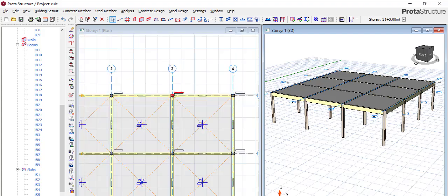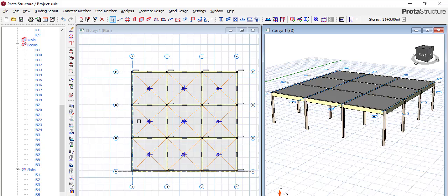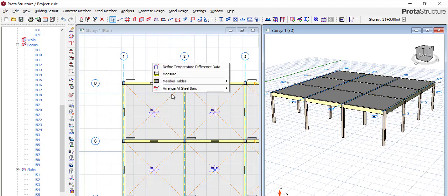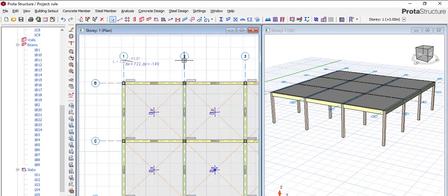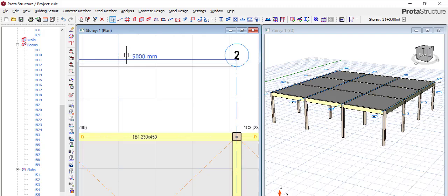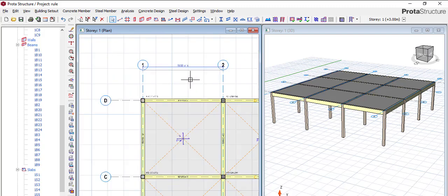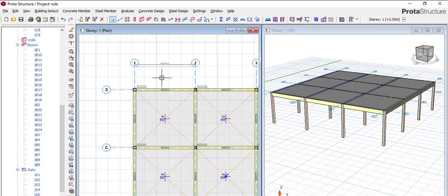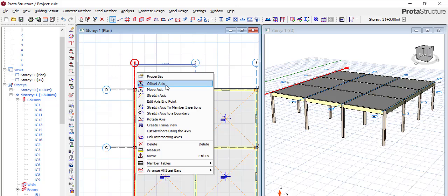We don't want the columns coming out, and so the first thing you need to do for this case is, let's assume now this is a 5 meter span. Let's assume the columns will come at the mid span or whatever span. If it's 2 meter from here, 3 meter, whatever the column position will be, that's very important. So what you do is to offset.